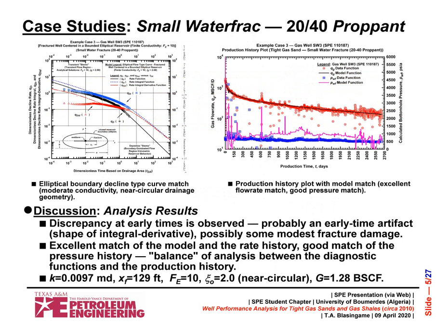So the very first case was a small stimulation case, and you'll notice that the gas flow rates are extremely well behaved, generally speaking. It's because they didn't have a lot of shut-ins in this field. You can see the calculated bottom hole pressures are down here. There's some disagreement between the calculated model-based pressure and the actual, or the calculated bottom hole pressure from a methodology, but we sort of attributed that to some of these wells producing water, and sometimes there was liquid loading.